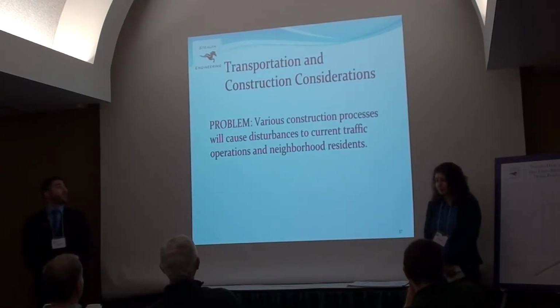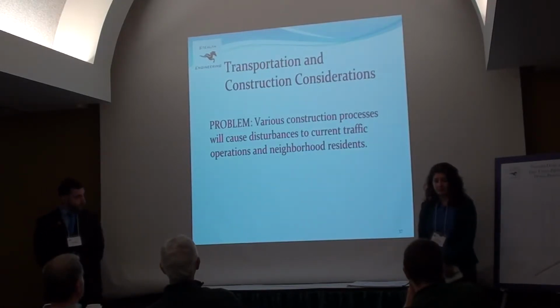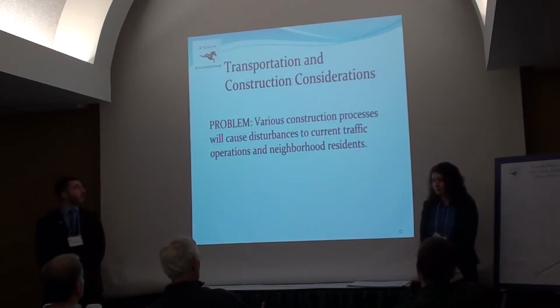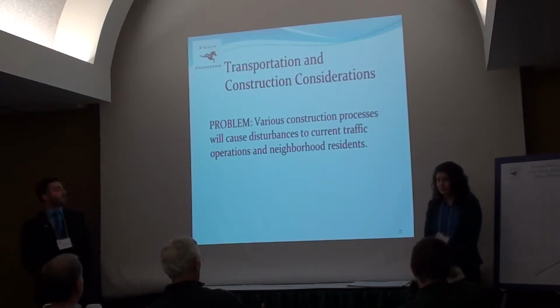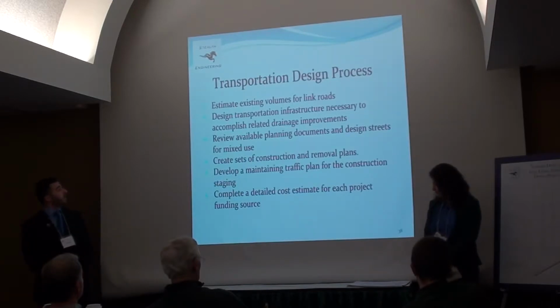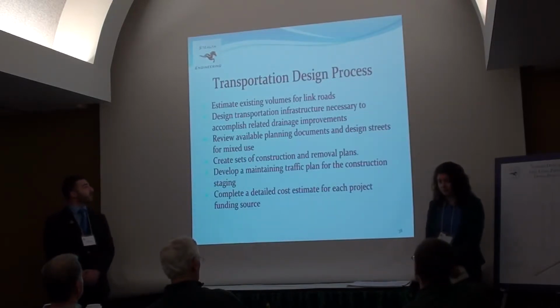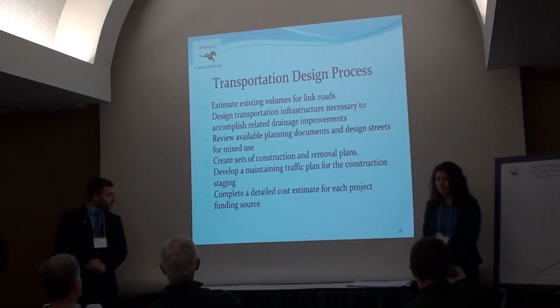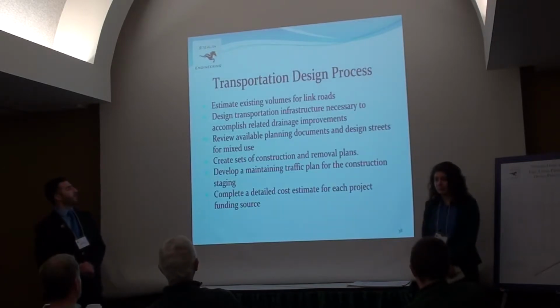As the transportation specialist on the project, the main goal was to maintain traffic during all phases of construction and ensure that neighborhood residents and roadway users are being safe. So the initial stage for the design process was to estimate existing volumes for the link roads on site. From here, we were to design transportation infrastructure to accomplish drainage improvements put forth by the hydrologist.